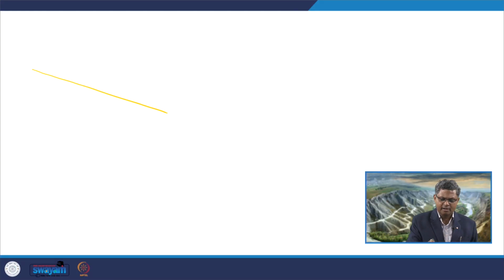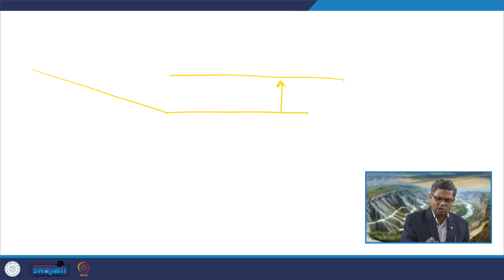So, if I think of, say for example, if this is the river profile, this was the base level at the start of the HST. Now, the base level is rising over here, and as a result of that the fluvial profile will try to reach over here. So, this is resulting in decrease in the gradient of the river profile, which will result in decrease in the energy condition of the river system. And in the initial phase, definitely this rises at a very high rate. So, during this phase what we will expect? We get more of aggradation than progradation.